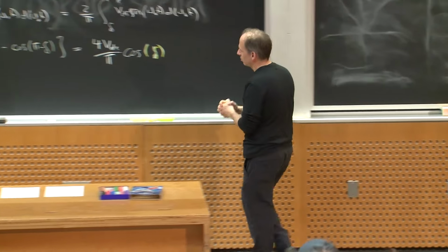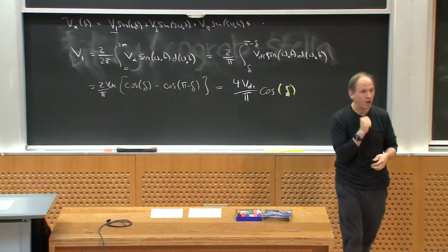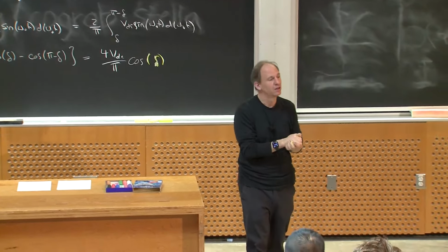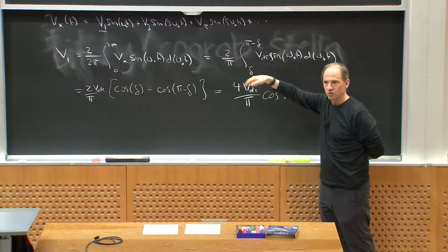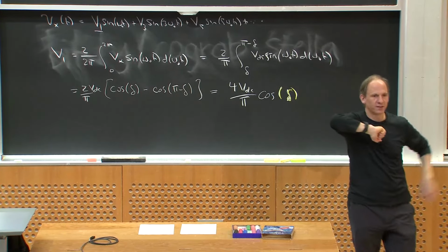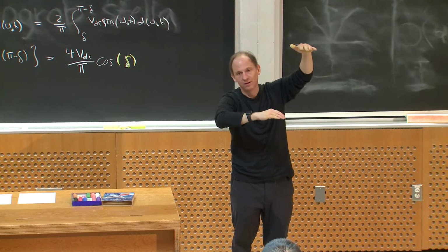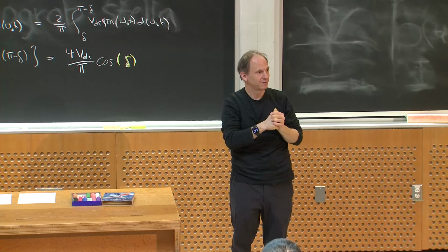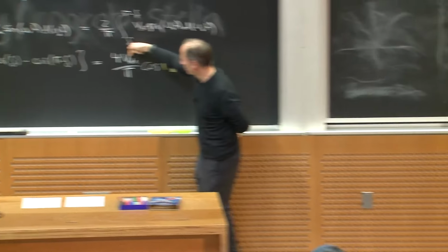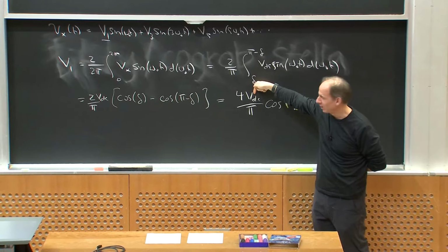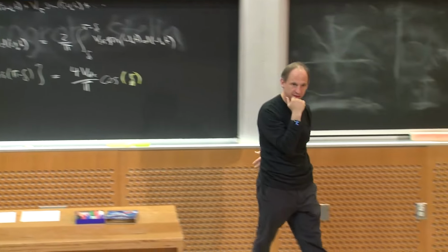What else could I do with this thing? Well, I can pick delta to control the fundamental. Another way to control the fundamental would be to directly control VDC, right? So in that inverter I'm passing around, they have an isolated DC-DC converter. Well, guess what? They can use that if they want to control the VDC that they get. So if you have a DC-DC converter before your inverter, you get to control this because you have a converter that can control it. All right? So maybe I don't need to use delta to control the fundamental. Maybe I can do something else with it.